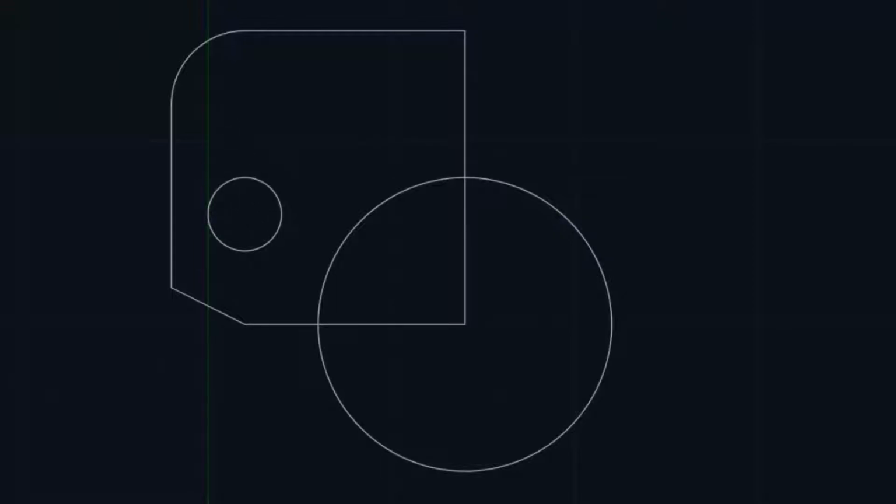So we're going to repeat that command, circle, come to this bottom corner. This time, according to the drawing, we want to go 2.5, so that's 1/2 inch, 1 inch, 1.5, 2 inch, 2.5, and upwards we need to go 3. So it's 1, 2, that's 1 inch, 2 inches, 3 inches, and click. Then we just pull it across 1 square and click, and that will drop the 2 circles where they need to be. So that's all 3 circles on the drawing now, but this one here will need to be trimmed out.